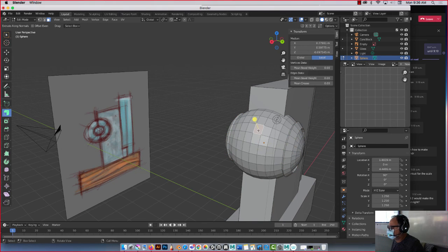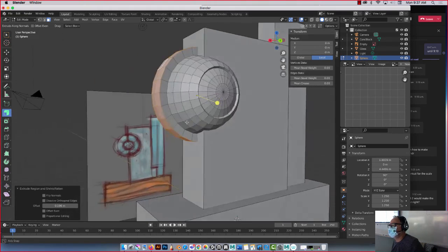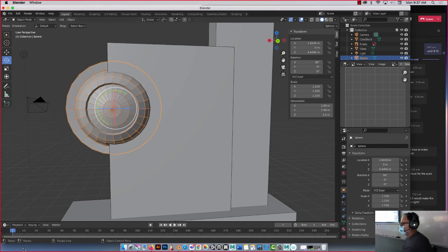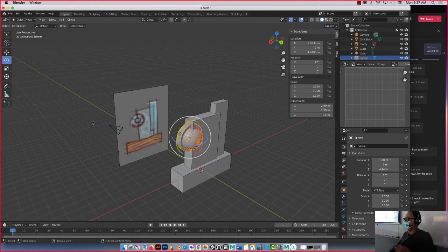Maybe I'll grab these two loops. Watch this. I'm going to hold Alt, boom. Hold Shift. Look at that. And then I can extrude this in or out. I just added to my design now, okay? I just added to my design. I had a new idea. So these are all lit up. So I'm going to Tab out, okay? I'll redo this again, extruding. I'll do just a quick chess piece for you guys to get comfortable with.